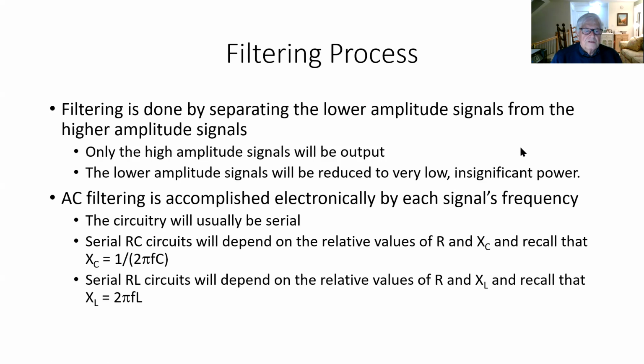So AC filtering is accomplished by frequency, using RC or RL circuitry, because we use the reactance, XC or XL, each of which depends on frequency.